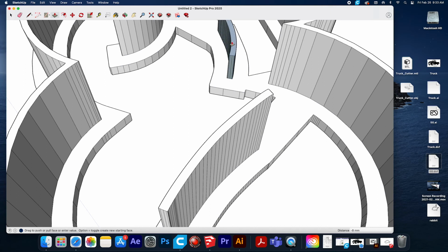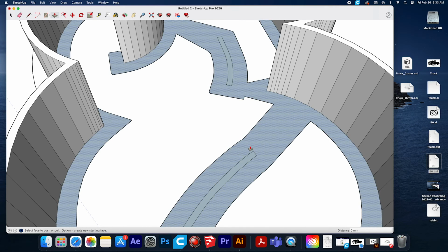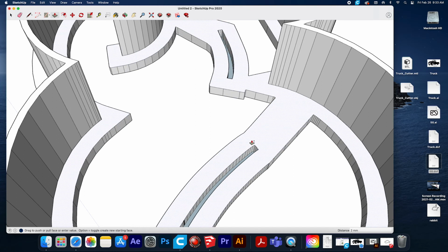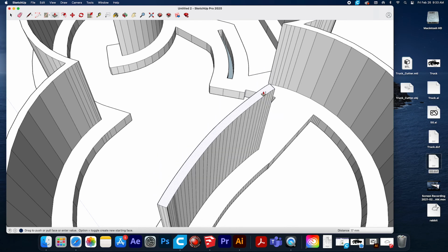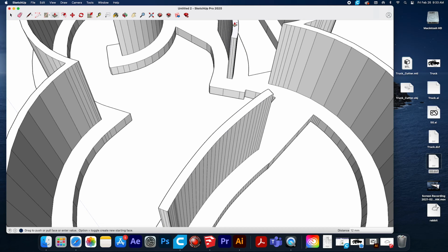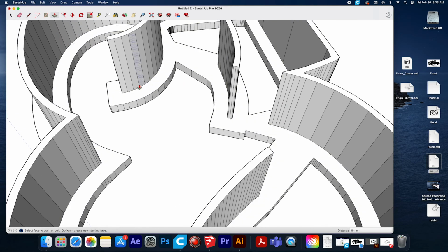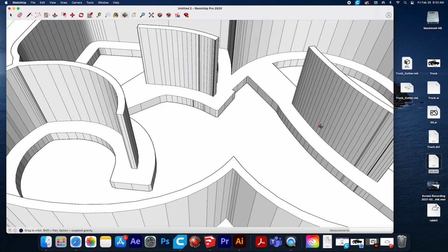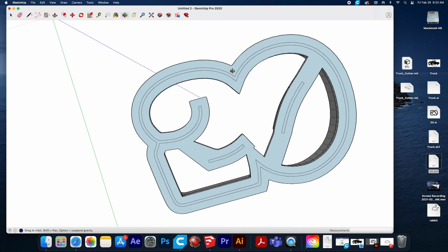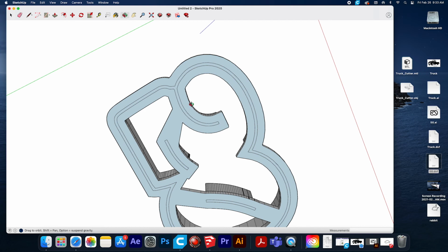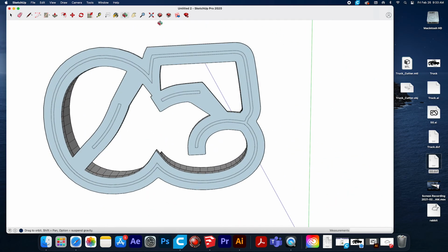I'm going to come up 16 and up. Oh, I did not hit the plus there. Let's just make sure that I did. 2 millimeters. So got the plus there. Make sure I get that plus. Okay. At this point, there's your cookie cutter. You got your frame so that it's nice and strong, and then it's just a matter of erasing these paths at the back so that it prints real nice.